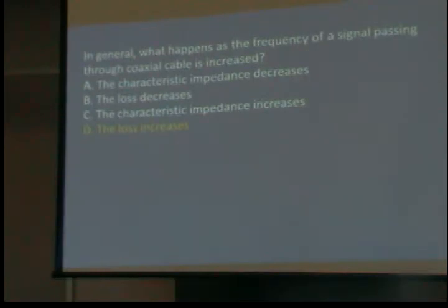In general, what happens as the frequency of a signal passing through a coaxial cable is increased? The loss increases. No matter what cable you buy, even 2.5-inch hard line at $20 a foot, the further up in frequency you go, the more loss you get per foot. It's just that where you start on the graph gets better.